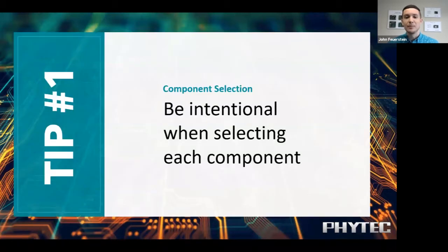Tip number 1, component selection. Be intentional when selecting each component. When you drop a part into your schematic, you should ask yourself why you selected that one in particular and build a habit of being mindful and don't just blindly copy and paste.